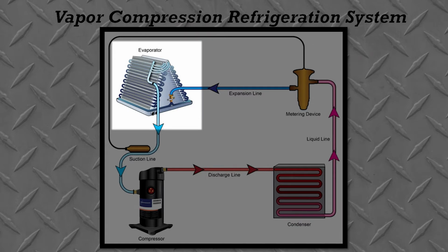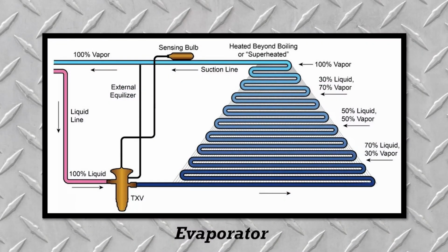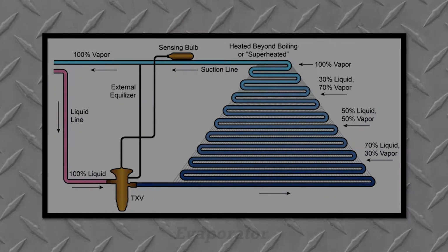As the evaporator changes all the liquid into vapor, it will suck energy in from the environment because it's now colder than its surroundings. And here we use gravity again to our advantage. If we have some combination of liquid and vapor together and we want it to come out just vapor, then we come in at the bottom with the liquid. As the flow goes through the evaporator, the vapor will travel to the top and let gravity separate it from the liquid, thus allowing it to leave the evaporator with 100% vapor that's ready to go back to the compressor.